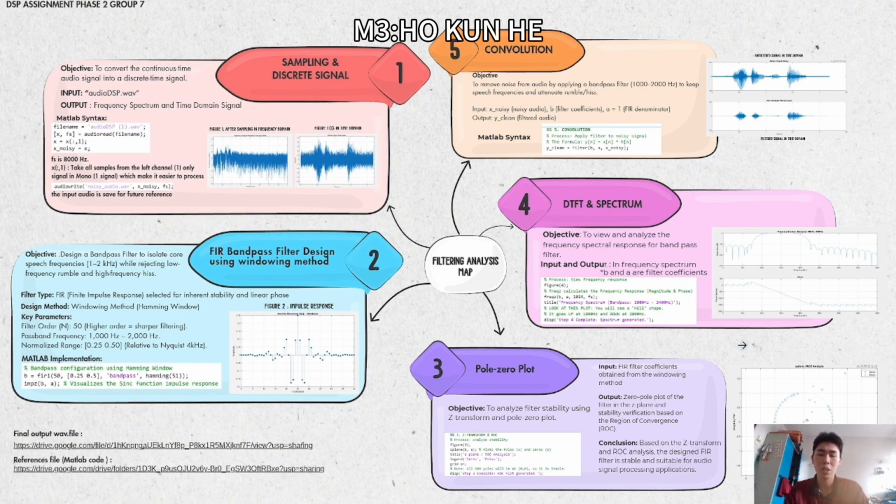The mechanism that we're using is freqz with b, a, 1024 and fs. B is the numerator coefficients from step 2, and a is the denominator coefficient, and the value is always 1 because we designed an FIR filter. The 1024 is the frequency resolution, and fs is the sampling frequency.